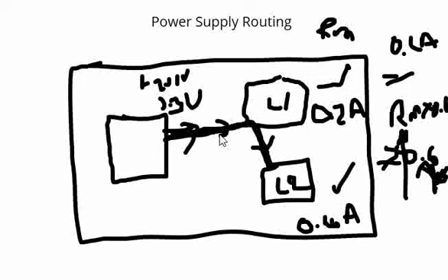then the voltage drop across this trace increases, and then we have to think about the logic level thresholds, and ultimately at one point, because of this voltage drop, it might lead to interface failure.